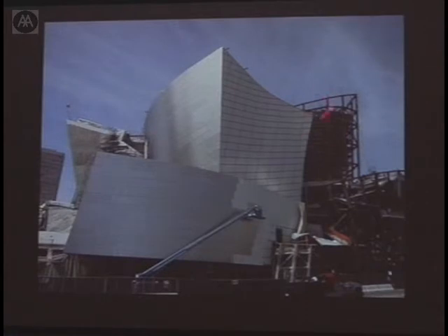Here you have already a fairly high-grade steel. This has a 3 to 4 inch tolerance on site, which means that if you imagine a center line through the steel, it can wobble within 3 or 4 inches on either side. And that's already pretty high precision steel. It's pretty expensive steel that you're talking about there. And still, the final cladding has a tolerance of just a few millimeters.